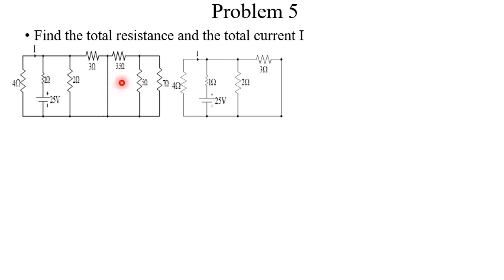So we'll redraw the circuit to this. So our new circuit that we'll consider in our analysis is this: the 4 ohm resistor, 1 ohm, 2 ohm and 3 ohm. So what do we realize from this circuit? We realize that the 2 ohm and the 3 ohm are in parallel. So let's use the approach I told you earlier. So we can circle from here to here to here to here without meeting any third element. We only meet the two resistors that we are considering, hence they are in parallel. So let us resolve that.